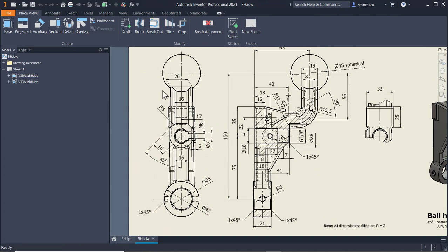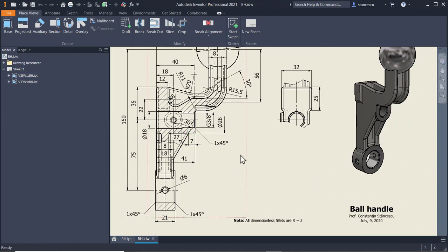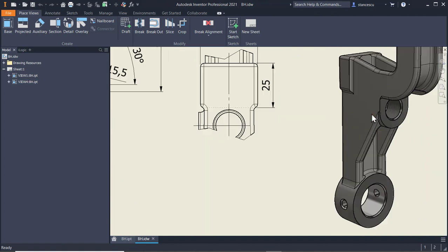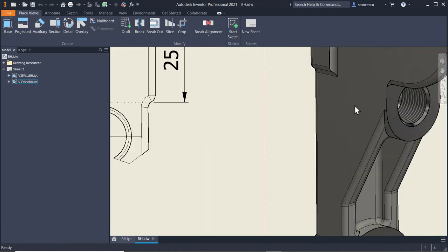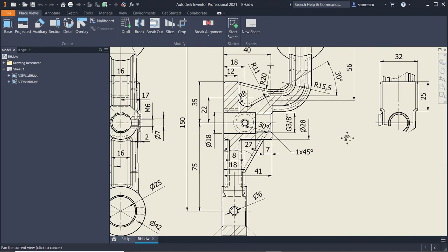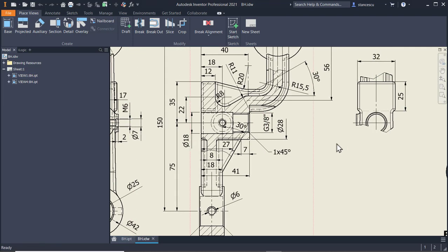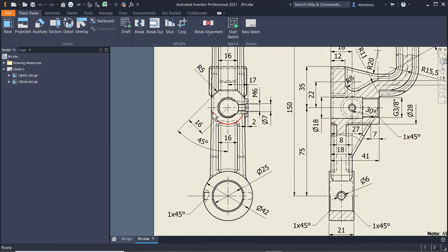There is a dimension here of 26 and then a tangency with this mid cylinder, which has no bumps here. So this plane must be tangent to that cylinder, and it grows to the left when you go down.